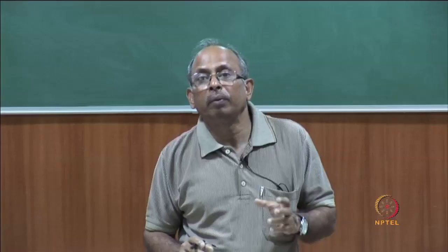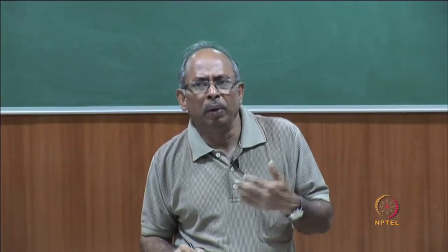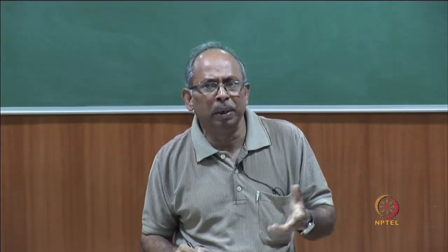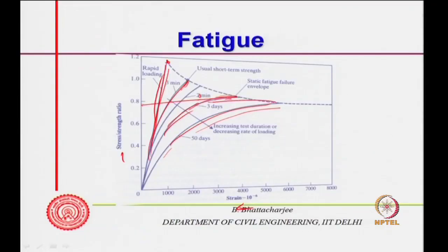Keep the load for 3 days, it might fail somewhere around 80%. I mean, this is a notional thing, one cannot take it for granted all the time, the values might differ from test to test. And if you keep it for 50 days, it will actually fail somewhere there. So, depending upon this, 20 minutes, 3 minutes, 2 days, 3 days and 50 days.